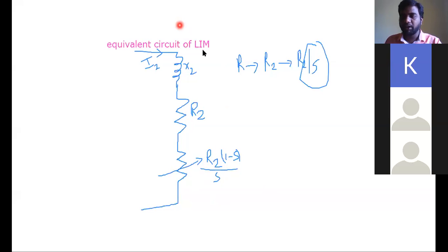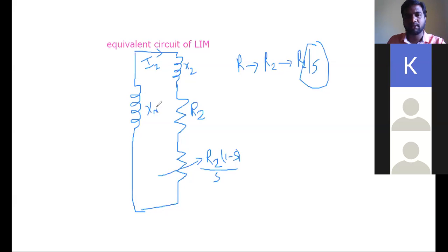Now we are going to consider a finite amount of reluctance as well as MMF in the air gap of a machine, right? In the air gap, flux will be available. So, in order to produce this flux, current is needed. So then the magnetizing reactance will come into effect, right? So now the magnetizing reactance here is nothing but the magnetizing reactance, that is X M, right?